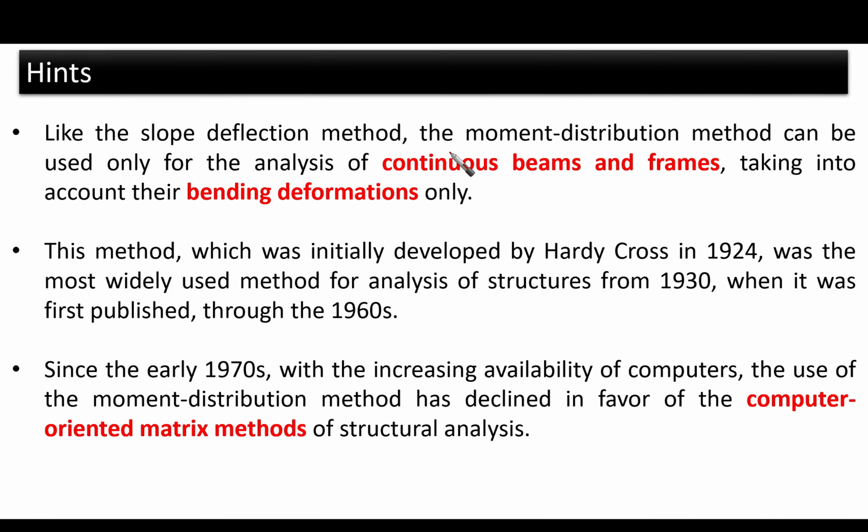They are the same in one thing, that they are suitable for continuous beams and frames. So like the slope deflection method, the moment distribution method can be used only for the analysis of continuous beams and frames, taking into account their bending deformations.